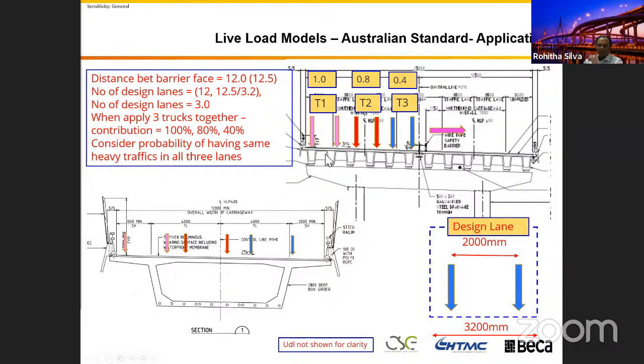If you were driving along the lane all the time, everyone driving like a robotic vehicle, you wouldn't need impact barriers at the end, because it would follow the sensors and the guidance provided along the lane, because the lane marking is there. You drive along that. But on the bridge, it's not like that. Humans drive. So because of that, this imaginary lane you can place wherever you want on the bridge to produce the maximum loading, right?